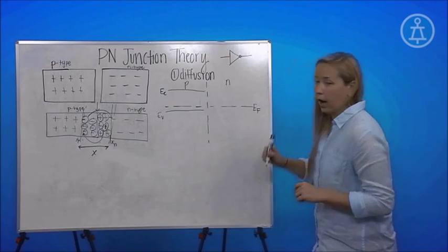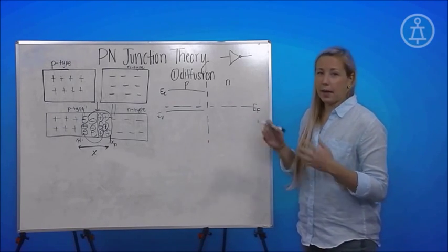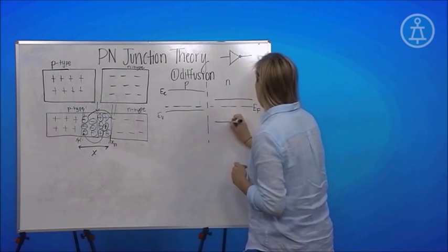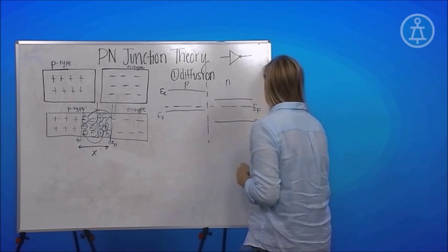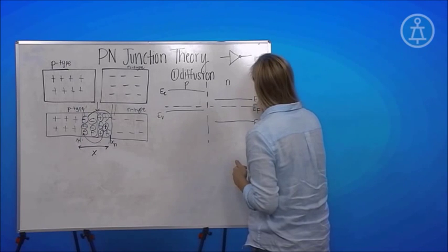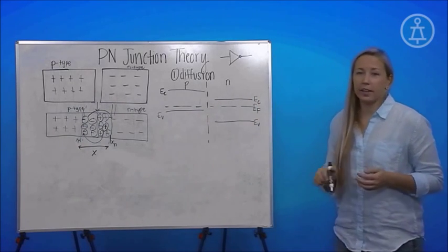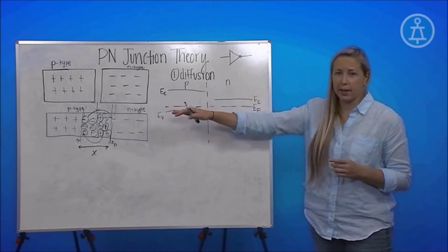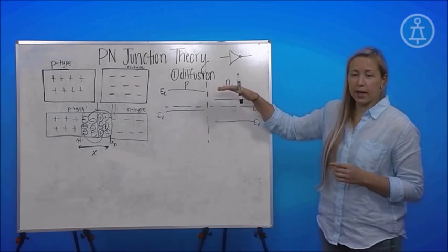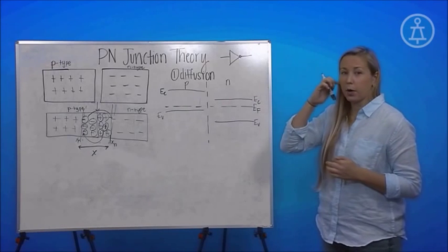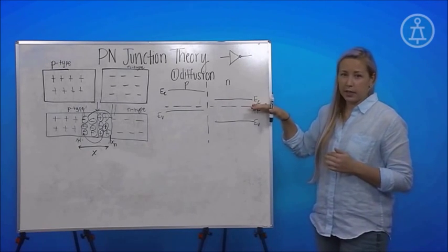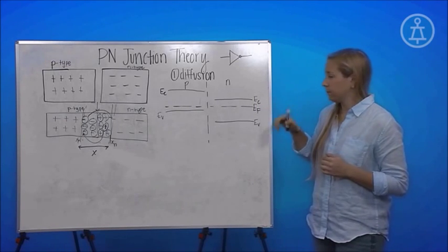And then the opposite for n-type, because we have more electrons to fill these energy bands. You'll recall that whenever you're doing an energy band diagram, the Fermi level has to be flat. So you draw the conduction band and the valence band according to the material type and with regard to its spatial difference from the Fermi level.